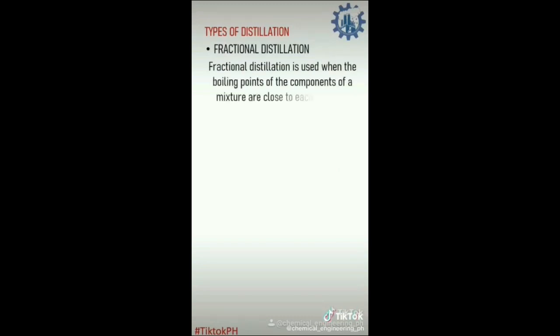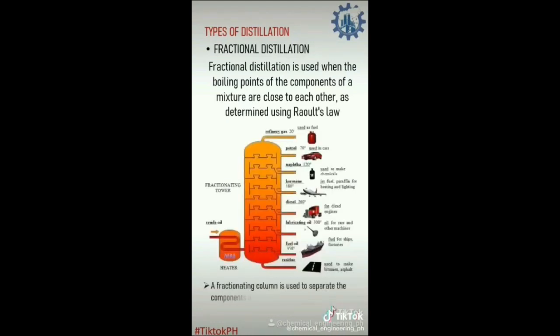Another example of distillation is what we call fractional distillation. Fractional distillation is used when the boiling points of the components of a mixture are close to each other, as determined using Raoult's law. A fractional column is used to separate the components, using a series of distillations called rectification.